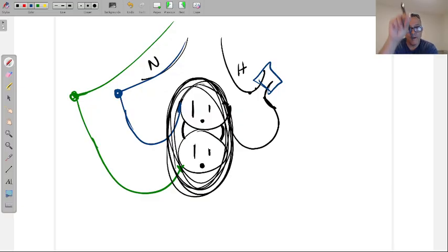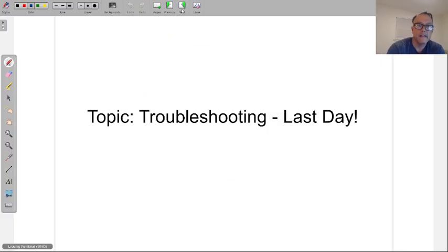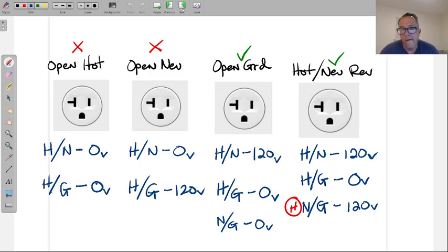And now also, as you're trying to get it into the mud ring too, because that's the other thing. Even if you spliced it live great, if you didn't do the electrical tape around it, trying to get it into the mud ring could be a little scary. Hitting the sides, and at least you don't get shocked, but. So there's a trick. Pigtails and splice. Same thing for a switch, and just make sure the switch is in the off position.